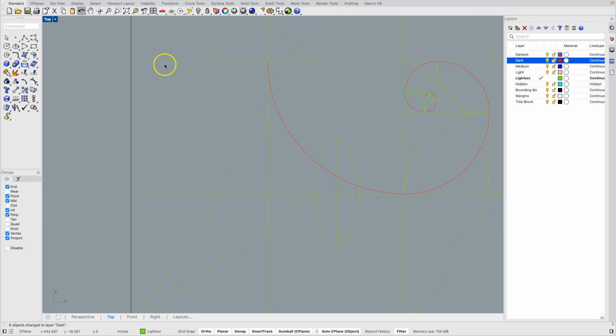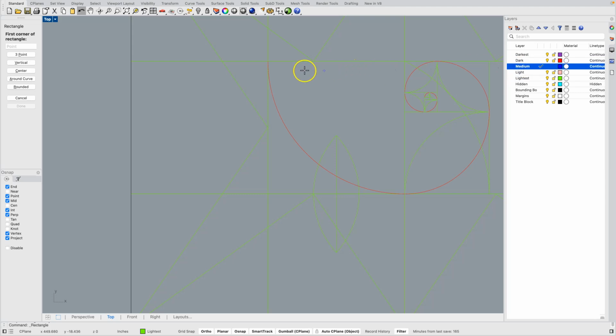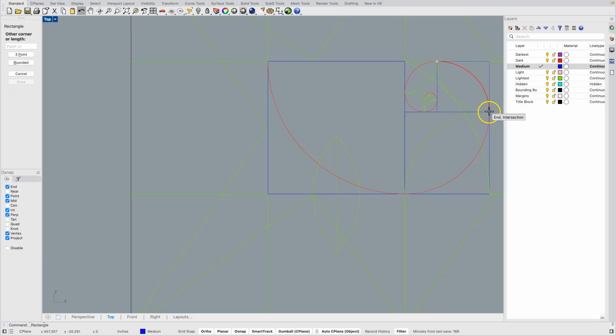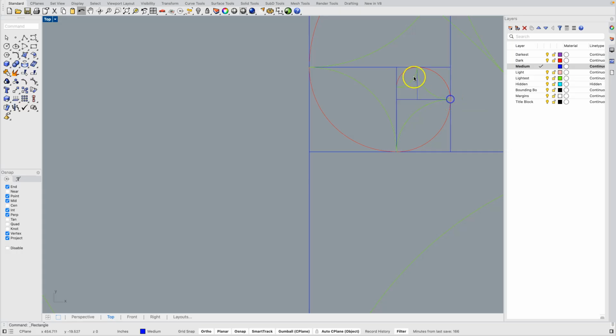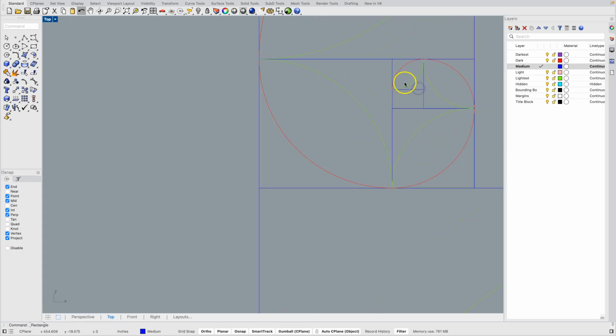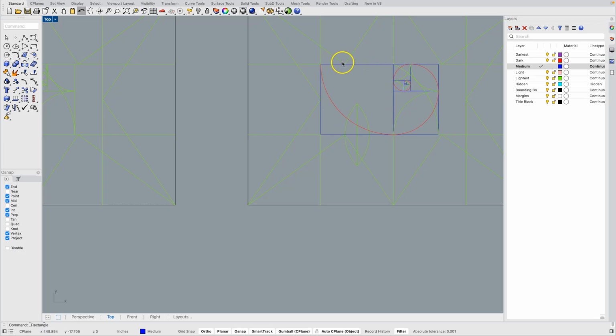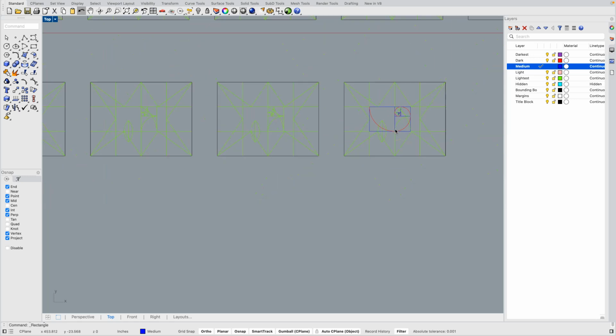That'll be a darker, thicker line weight when I start to export, and I have my thinner guidelines. But maybe I also want to play with the fact that I just drew these squares. So I can come in here, go to medium, and maybe I want to use slightly lighter line weight. And I'm just hitting enter to subdivide. And now I have a slightly thicker line, that medium, and that will pop. That'll be a thicker piece than the other sort of guideline geometry.